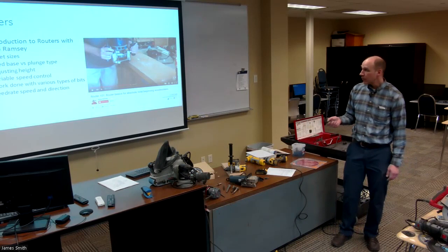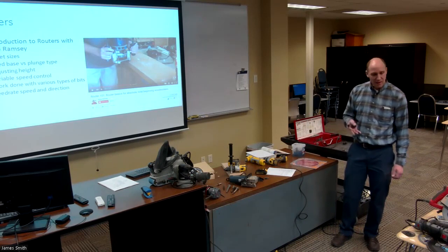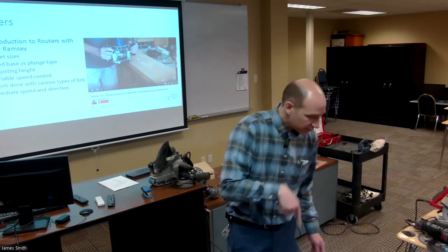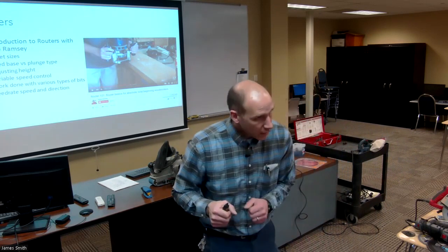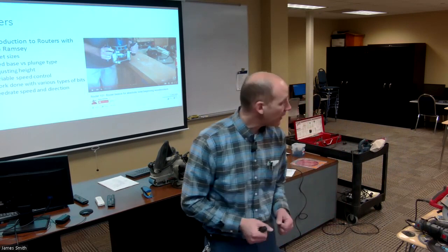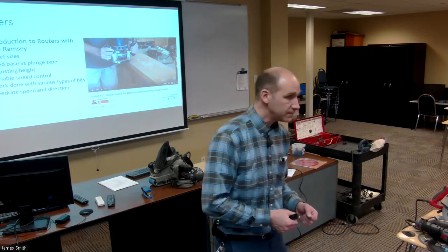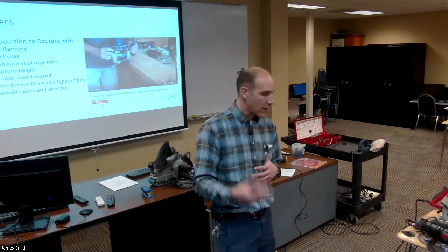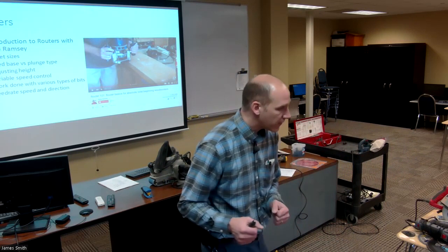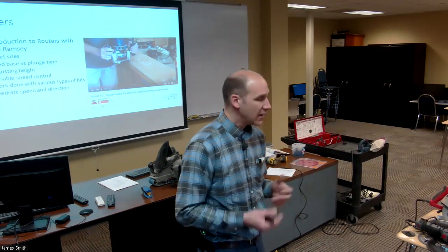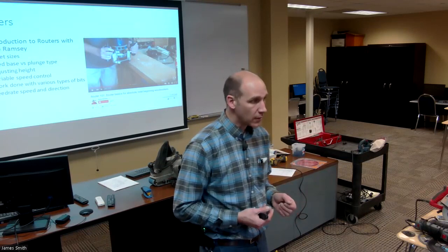I think we went through all this. Oh, as you're routing things, the router turns a certain direction. Which way do you feed? Do you feed with the rotation or do you feed against the rotation? Against, that's right. When you're running the router, you want to push up against that cutter rotation, and that's going to give you better control.